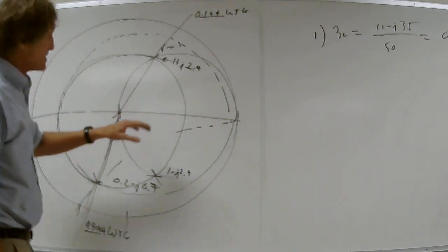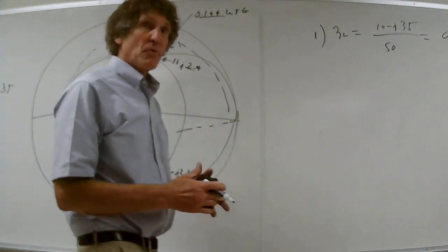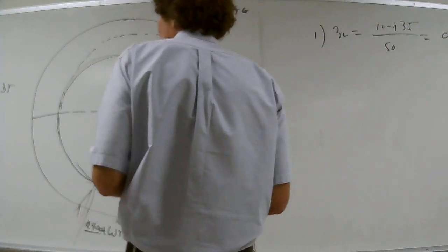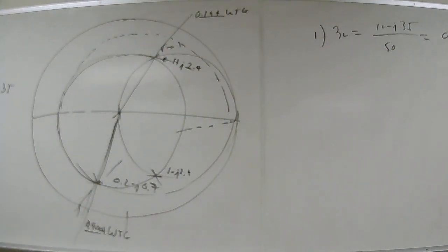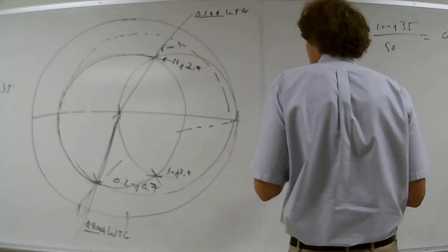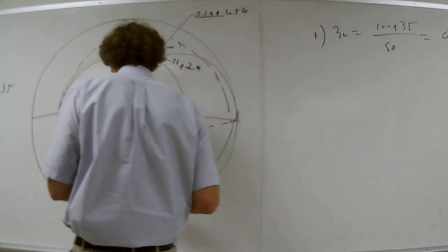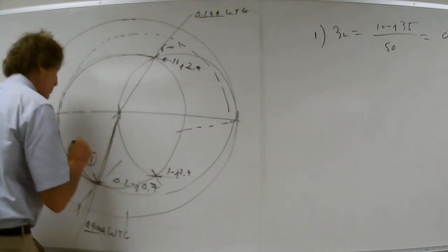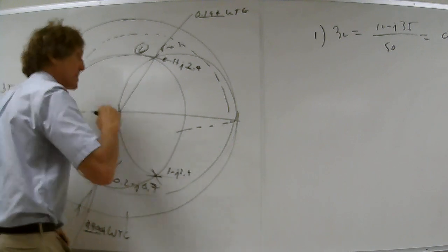All right. So this has a real part of 1 and a reactive part of J 1.4. We have to add a reactive part right here. Its normalized value would be minus J 2.4. That would be the normalized value, correct, class? You all follow me? All right, so I'm going to come over here and label these things, as I do on tests. This is point 1, this is point 2, the second point.